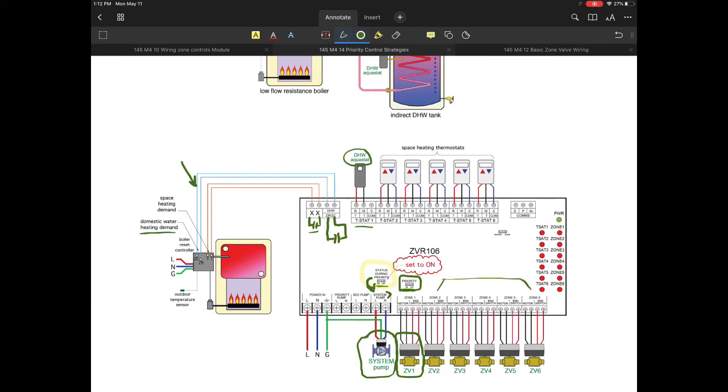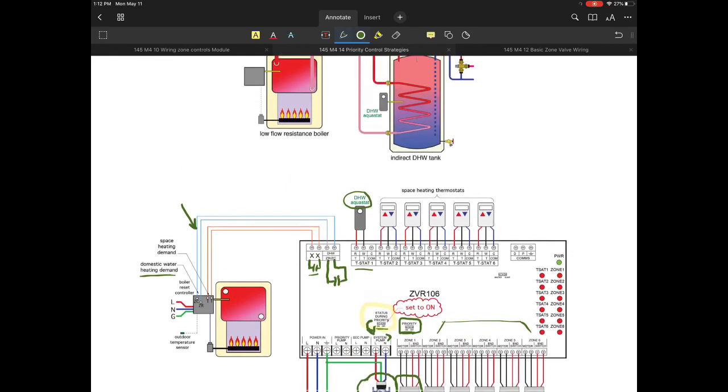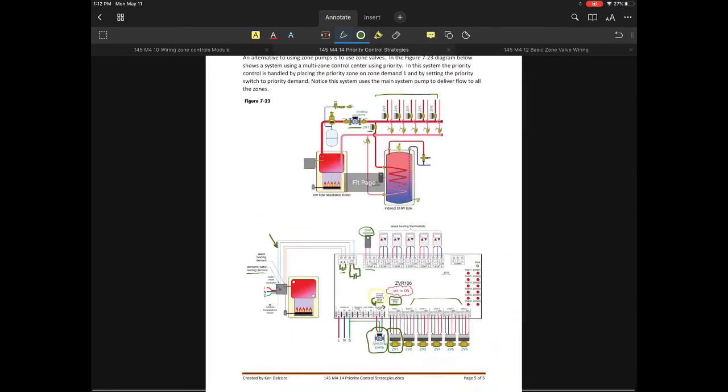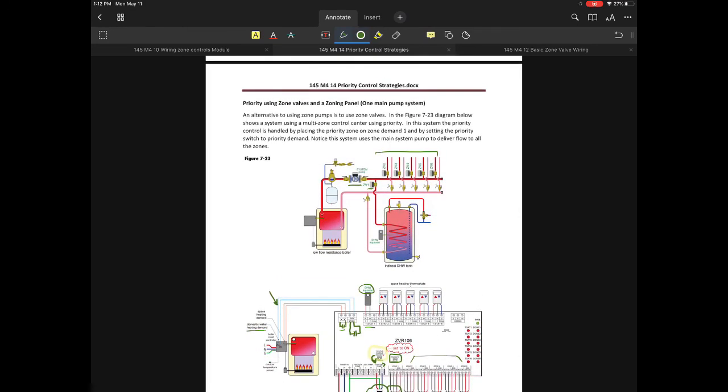So if you ever are involved in the field and wiring these types of applications for zone pumps and zone systems, I would strongly encourage using a zoning panel of some sort, whether it's by Caleffi or Taco or Bell & Gossett or Honeywell or whoever makes them. It sure makes troubleshooting and diagnostics so much easier. Not to mention that it also gives additional features that are maybe available on some of these, such as pump exercising and ways to control it.